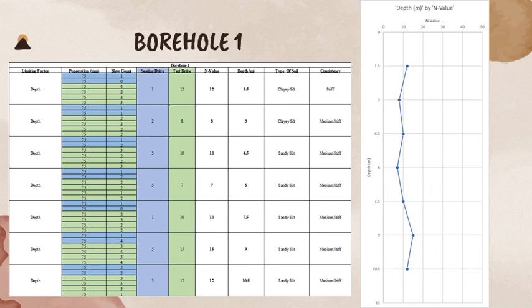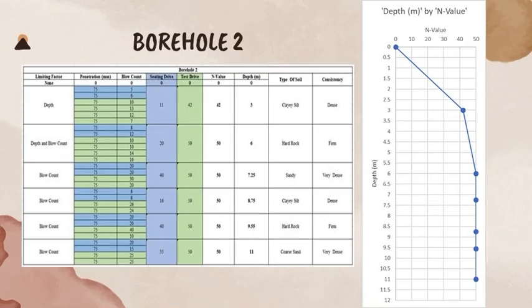The SPT N value is taken from the test drive, which is the number of blow counts that are taken after the first 150 millimeters of penetration. The data is grouped in intervals of 1.5 meters in depth. Therefore, the limiting factor would be depth, which is 1.5 meters. Based on the source of our bore log, we can determine the type of soil and the consistency of the soil at the 1.5 meter depth intervals, which are also tabulated in the table above. The source of our bore log can be seen from the reference page of our written report.